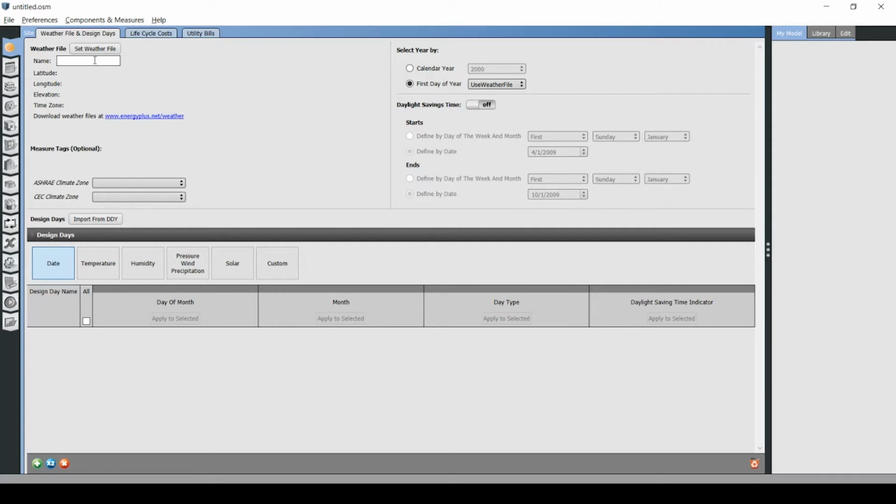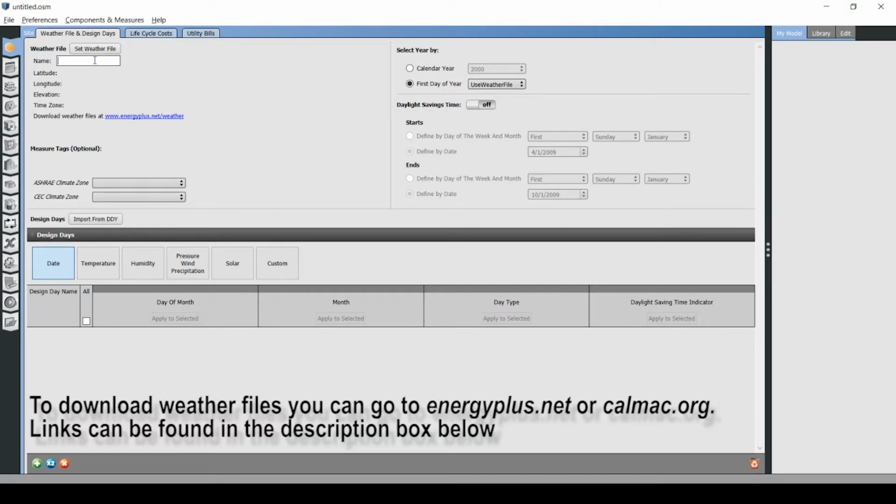Now let's begin with an empty OpenStudio model. Normally, weather files are required for every OpenStudio simulation. These files can be downloaded or purchased from several different sources. The Create Prototype Building measure will import a default weather file into our model for us, so we will skip this step.